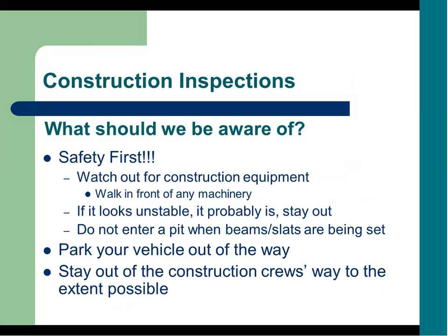What should we be aware of? Safety first is always the case. Watch out for construction equipment. If there's some big equipment being operated, make sure you make eye contact with that operator. Make sure he knows where you are. If it looks unstable, it probably is. Stay out. Do not enter the pit when beams or slats are being set. You never know what's going to happen when that's going on.